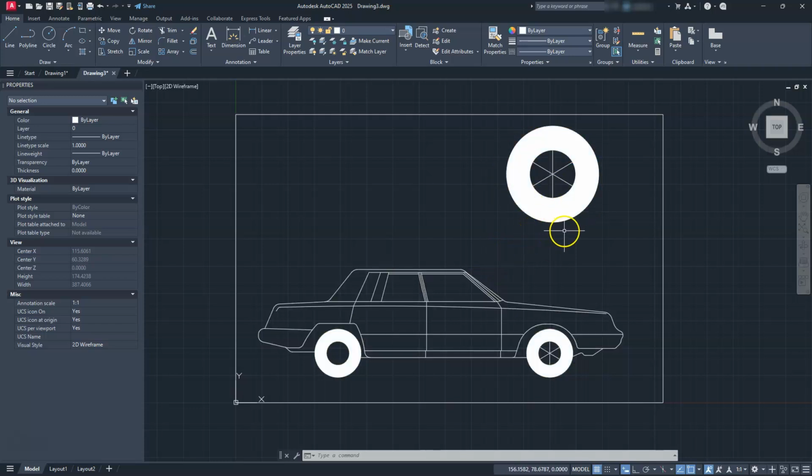Now I have to put the scale down below this one and tell somebody that this has been scaled up. You know, you can put not to scale under this as well, although it's not accurately correct. But if you couldn't figure out what that scale factor was and you actually put not to scale underneath that, technically you're not incorrect. But it's nice to figure out what that scale is. All right. So this takes care of everything that you have to deal with here in model space, right? So that's the exception to the rule. Now, if I'm going into paper space now, and I'm just going to erase all of this stuff.